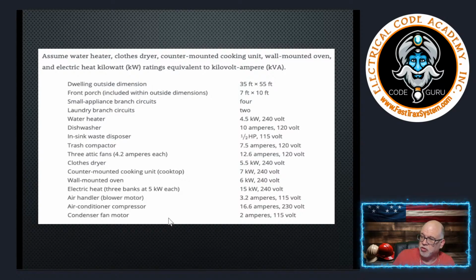So it's only the 240 volt loads, except for the range and the dryer, which obviously you electricians are familiar with, right? We're going to run 4 conductors to those, and they have some elements in there that are going to need 120 volts. So definitely we're going to have some neutral loads associated with the dryers and the ranges. We will take care of that as we move through it. But just so you know up front, they're going to be at 70%, and we get that allowance in 220.61(B). So anyway, we'll work through those type of things.